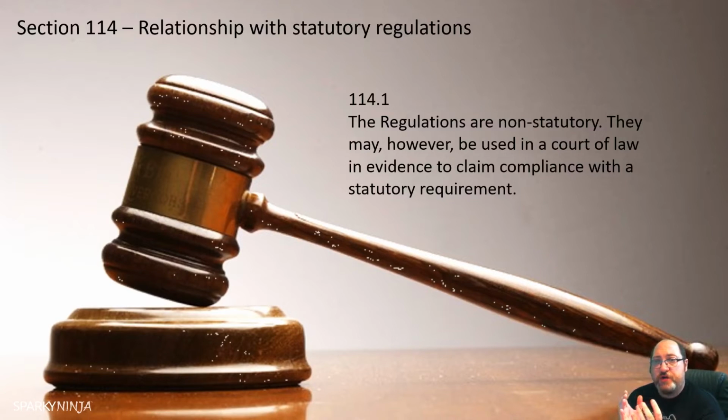So any electricians that go to those firms, they comply with BS 7671, but they also have to comply with the rules of the company. So it might be that the company has chosen a brand of this or a brand of that, because all they're thinking about later on is what they've got to maintain once you've installed it. So they have a spec or a method of work that both helps them maintain in the future and ensures safe working practices when you're there. So these are examples of other controls really that you could have.